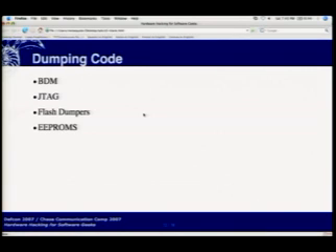It supports a lot of the same stuff as BDM. Basic JTAG won't let you do debug. It won't let you step the clock one step at a time. It won't let you access the registers. It will, however, let you set or clear the state of any pin around the device.